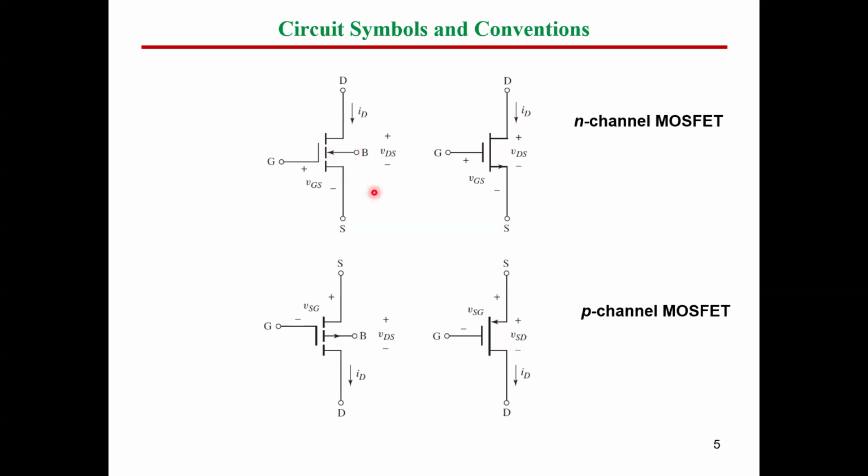Okay, and a third dash here represents the source, and this here is the gate, and there is a space. As you can see, there is no connection between these three dashes and the gate. So it can be like a symbol of the capacitor, the internal capacitor of the MOSFET. So this is now the symbol of the MOSFET.